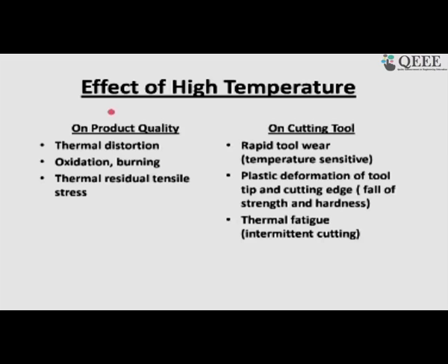That means the work material becomes the solvent and the tool is the solute, and the material is eaten up, and then there is loss of material, which means tool wear. So, it is temperature sensitive. Then plastic deformation: the tool does not hold the required hardness, the retention of hardness is very much affected.